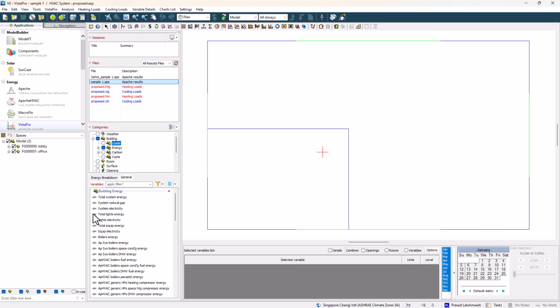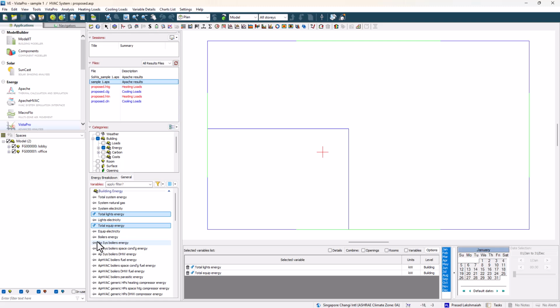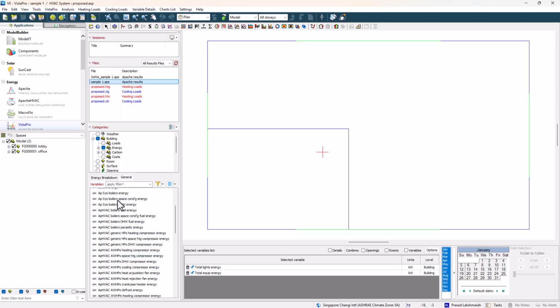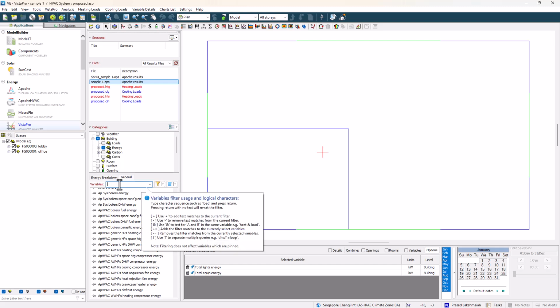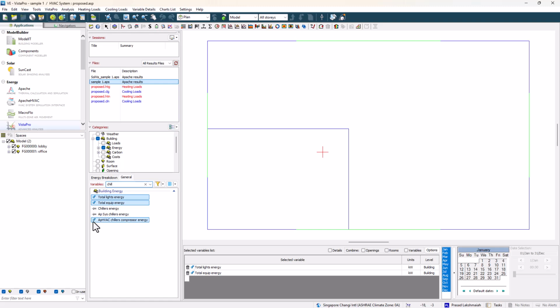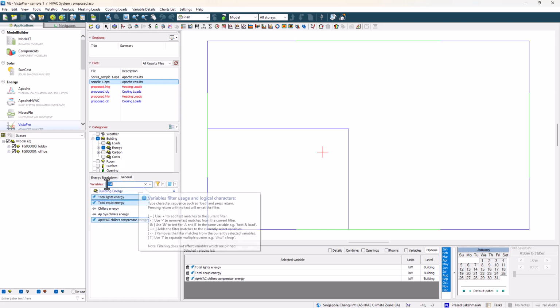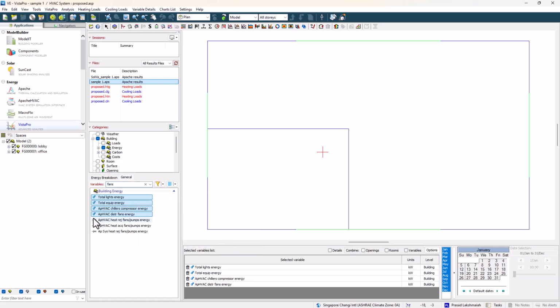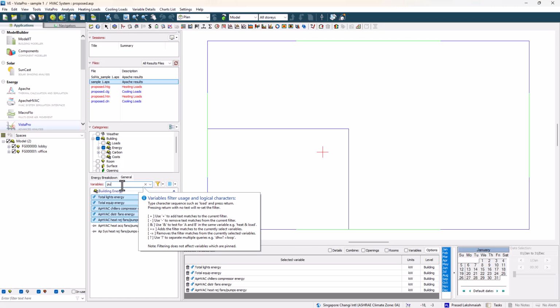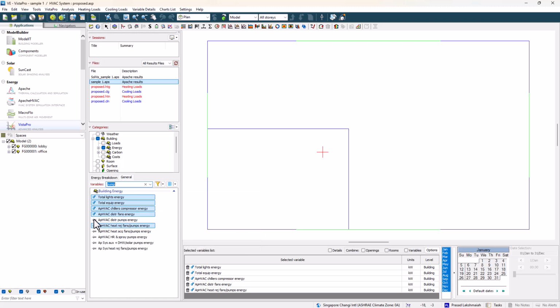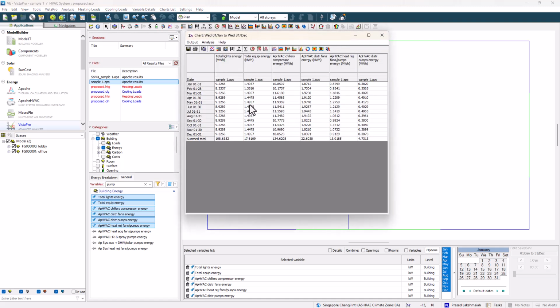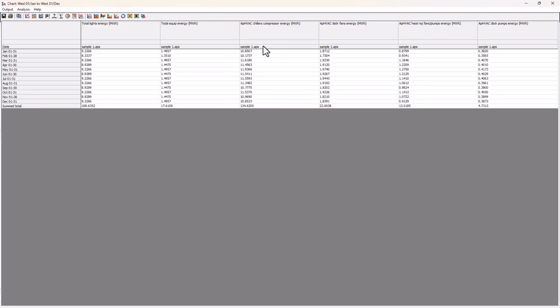Comparisons of simulation results can be made after every change and at every step of the project, from conceptual design onwards. For example, the difference in energy consumption across a full year. For existing buildings, we can also calculate NMBE and CVRMSE as part of ASHRAE 140 to check that our model has been properly calibrated by comparing the simulated energy to the actual metered energy use. There are also options to export general results using predefined reports, or to review building-specific detailed results as images, graphs, or tabular data.